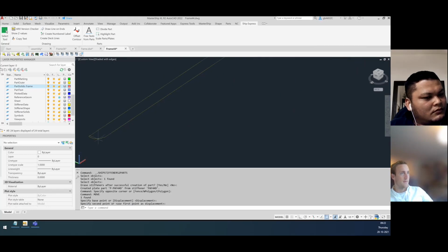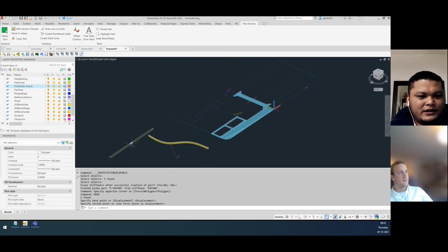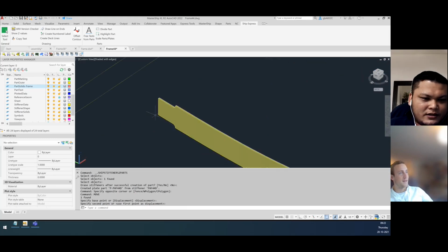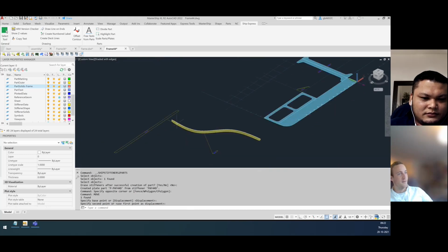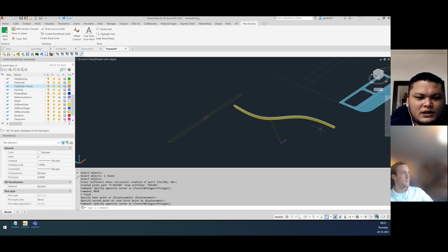So now it's flat. And then you can send it to a cutting machine. That's maybe easier, since if you have to make this in a workshop, that's simply too hard. So maybe it's easier to cut. So that's what this command does. It simply expands your stiffener.